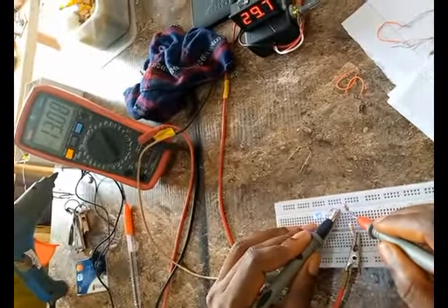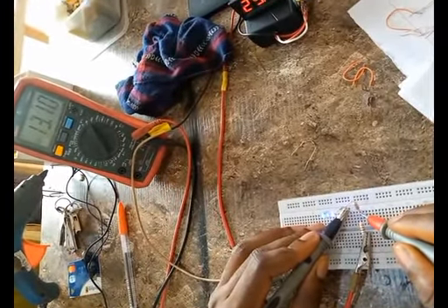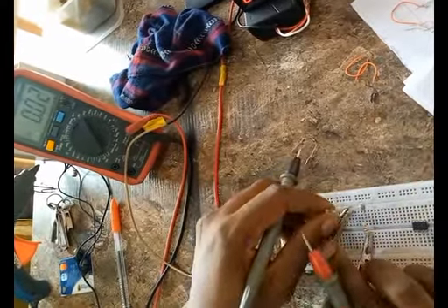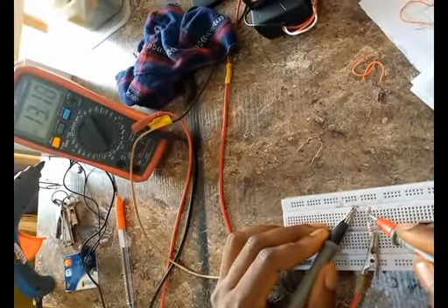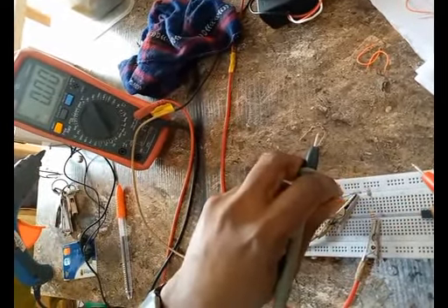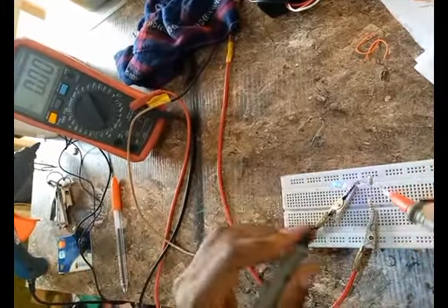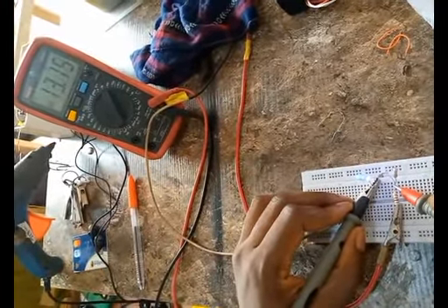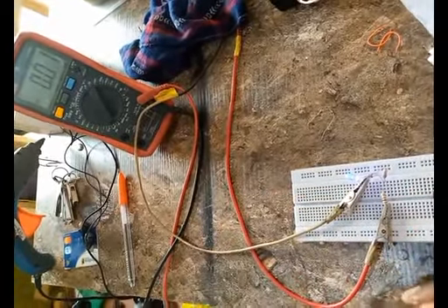Around 13, and that's because an LED is just a small load. Remember, what we had before the LED was introduced was higher, about 13.16. But with the LED connected, it drops. You see that, 13.15. The LED will just draw a little current.